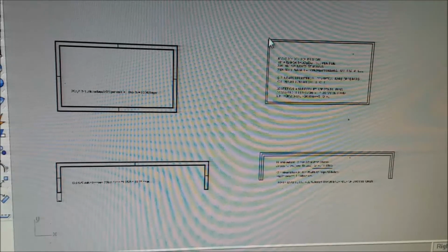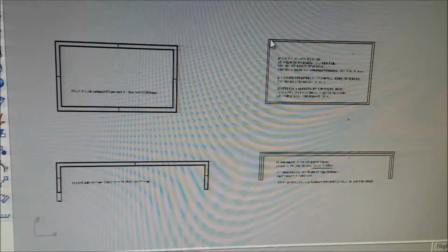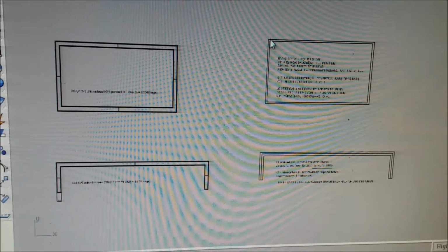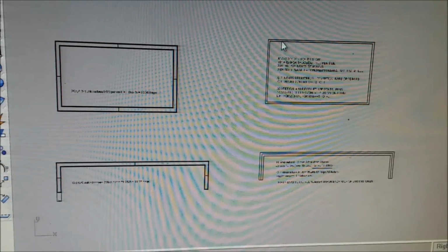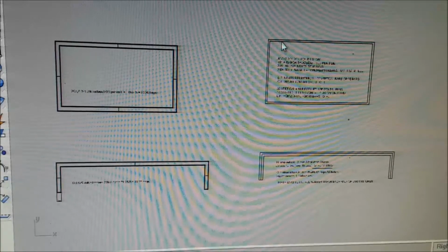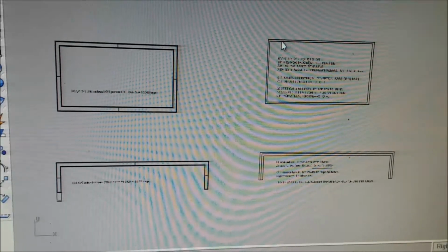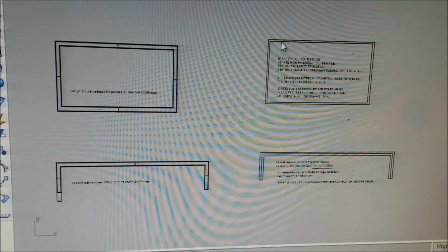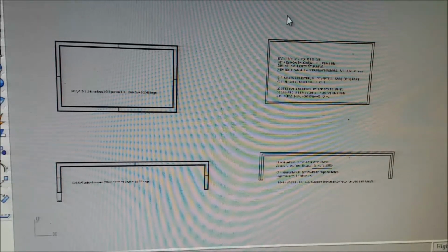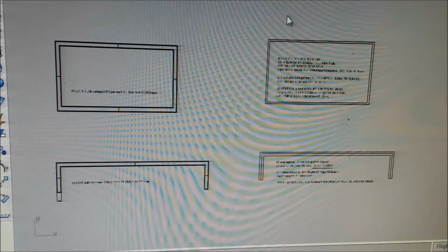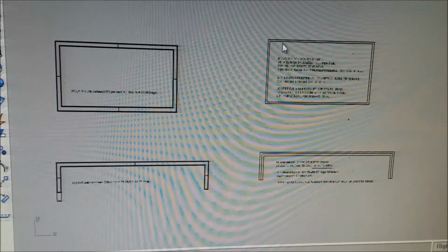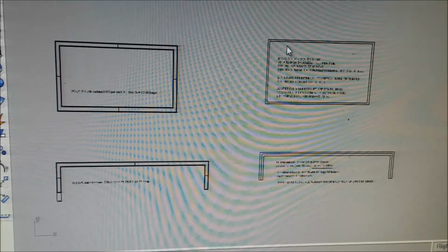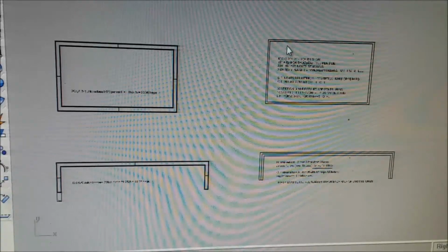If, like, we have upper tie beams that are 14 inches wide, so we have 14 inches of width there, 7 inches of it can be for a floor going this way, and we can do a second pour from there over. We don't want to pour an entire slab over a day and a half. We can break it down into less than 80 bags a day.